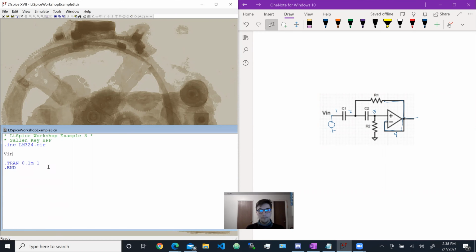So let's do a VN, and we're going to say from 0 to 1. This will be right here, 0 to 1. And then I'm going to say AC 1. Okay, just making sure I didn't forget anything. AC, and it's going to be alternating just 1 volt.